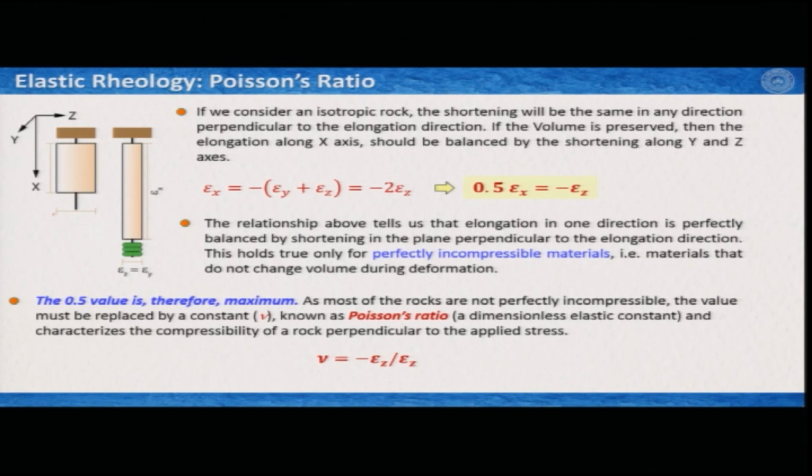So, this was initially the width of this bar, say this is a spring and this is the length of this spring. Now, upon applying this load, these green bars, then I can figure out the strain which is along x direction, which is epsilon x, and if I consider this is cylindrical and a perfectly isotropic body, then on this direction it has to shorten to keep the volume constant, and therefore, epsilon z and epsilon y should be equal.